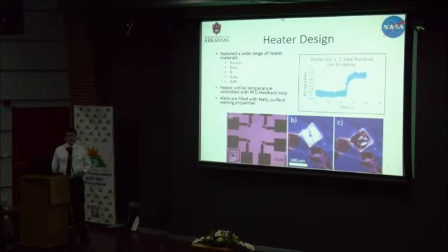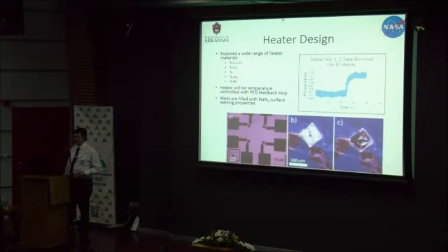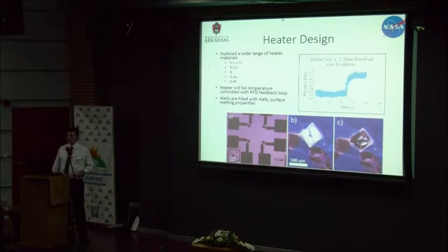I've investigated a number of different materials for the heaters. I started with Ti-copper. Both of those are bad because the copper is highly corroded by the sodium azide. Titanium works well on its own, but you have to grow a pretty thick layer for the resistance to be suitably low. So Ti-gold worked quite nicely. However, it burns out at a lower temperature than I like, so I stuck with titanium-platinum. That is what I'll be moving forward with. A really nice feature of this as well is that I can drive these heaters and, using a feedback loop, I can control their temperature because of platinum's RTD performance.